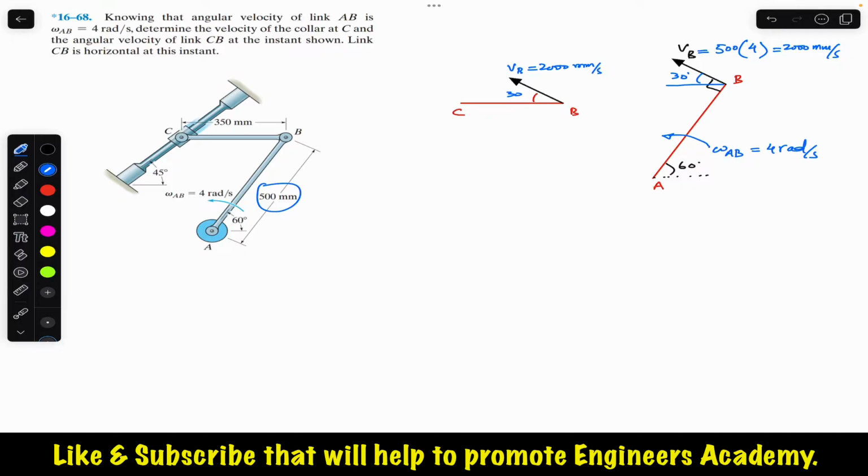And similarly, the velocity of C is going to make 45 degrees, right? So we will have the velocity of C here. This will be the velocity of C, and it is making a 45-degree angle, since both of these angles are alternate angles. So this is the velocity of C.